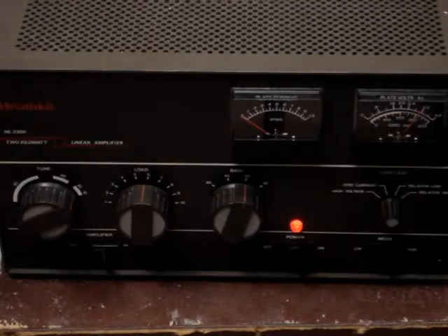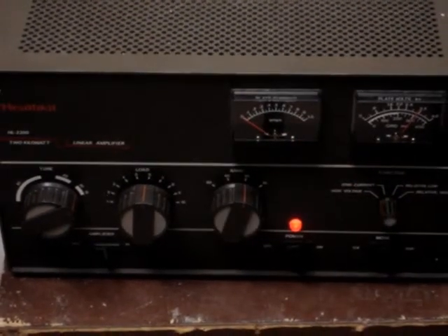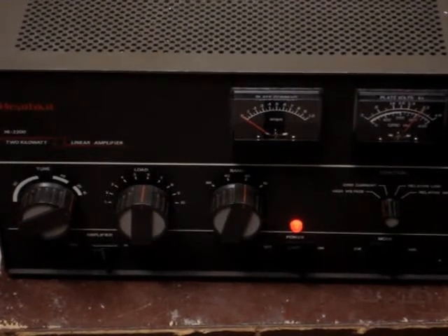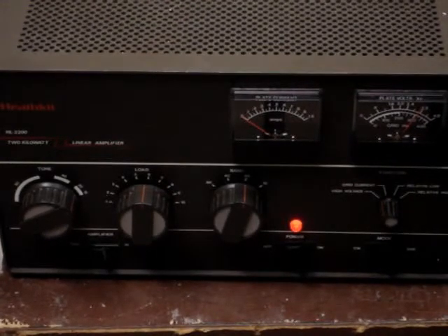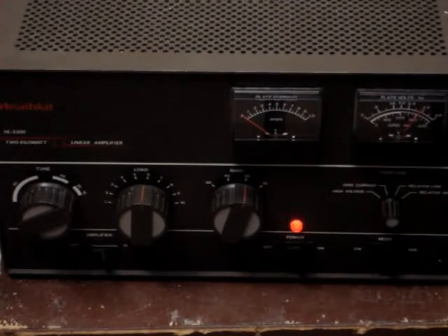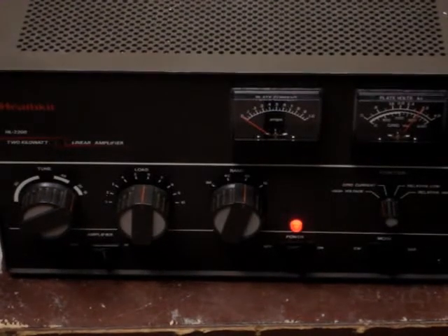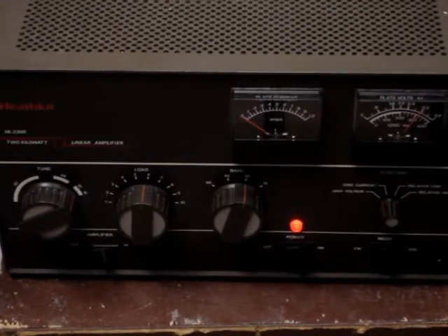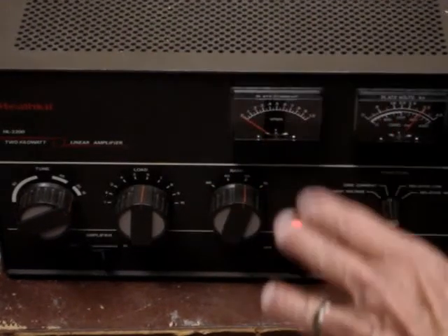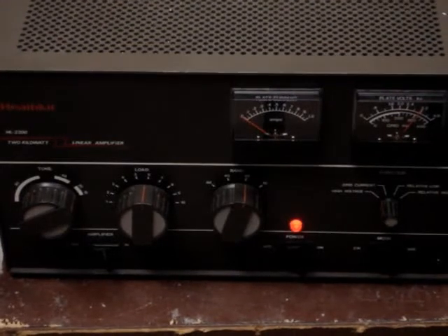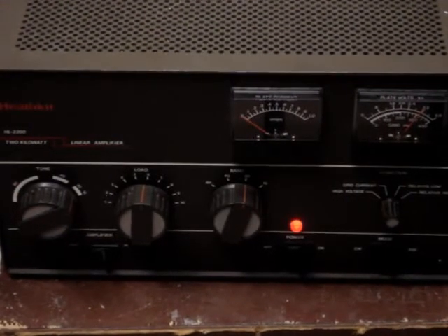Okay, now we have the amplifier turned on here. It's in idle mode, and notice when we key it up, there's just a little blip at the beginning, but the current is really low. I can't see it, but it's not there. Now when we let go, there's a little blip, and then I have my QSK 2500 box in there, so there's a 3-second delay when I let go of the PTT. But it's kind of unnerving at first to look at your plate meter when it's keyed up and see basically no current. Okay, now we're going to put a little RF to it.